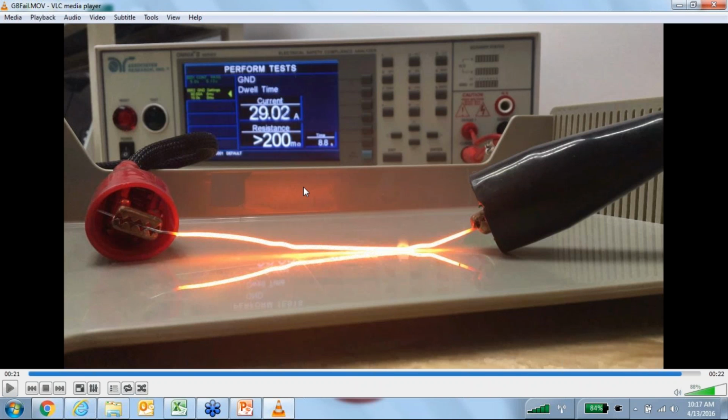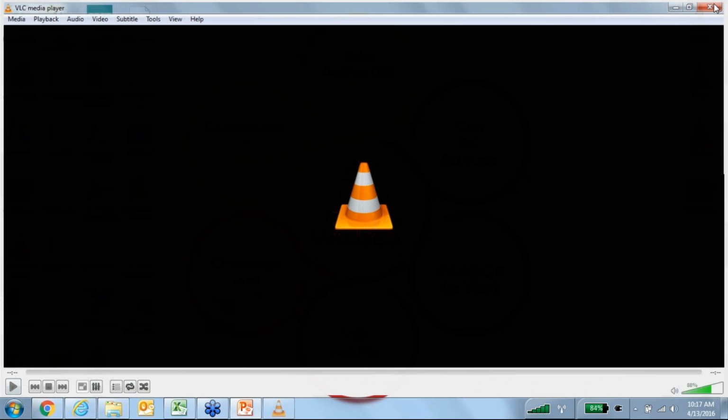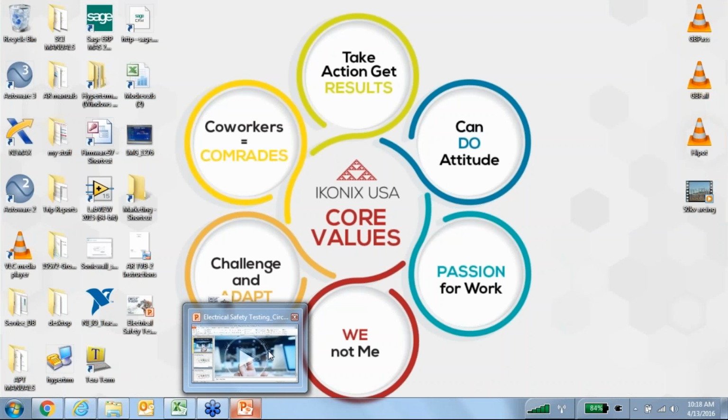So normally with your tester, if you would fail, it would never reach this point because you would have your high limit set, and once the current meets resistance that is too high, it's going to tell the device this is pretty much an open to me because I can't flow any further, or the resistance is too high, so the test has failed and your output will stop. So again, this is kind of to demonstrate what a ground bond pass and failures look like.